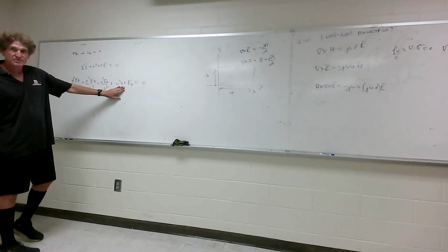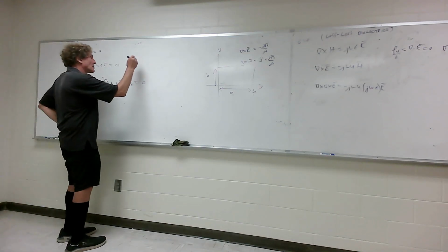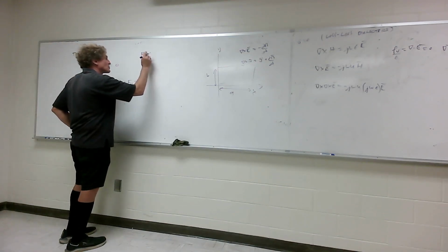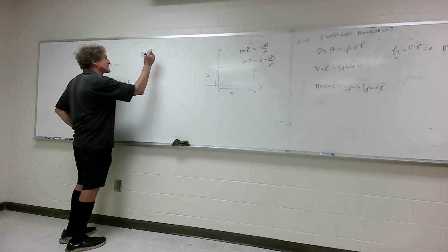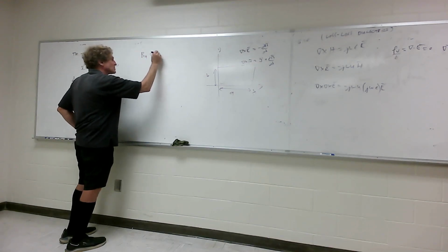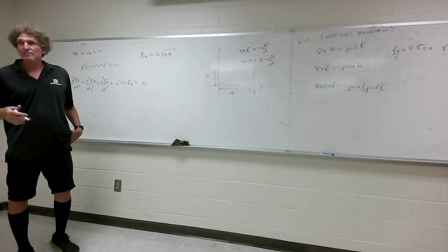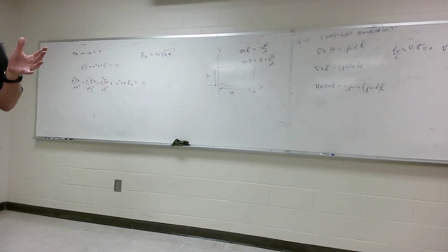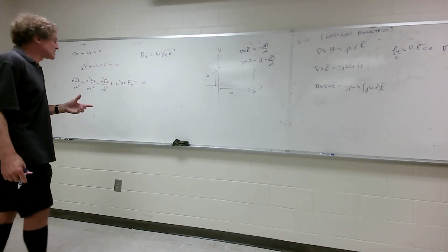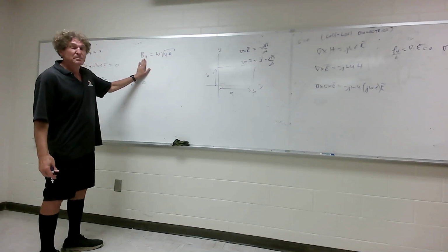First constant is this one. Wentworth's book calls it beta, or just beta unguided here. And he's going to say that's equal to omega square root of mu epsilon. The reason he does that is because if you think about free space, it's not in a waveguide. It's just waves propagating in the atmosphere with nothing binding them. Follow me? There, if it's a lossless media, beta has to equal omega times square root of mu epsilon. Do you remember this, guys? So that's why in Wentworth's book, if you've got a book, you can look at this. He'll use beta unguided.